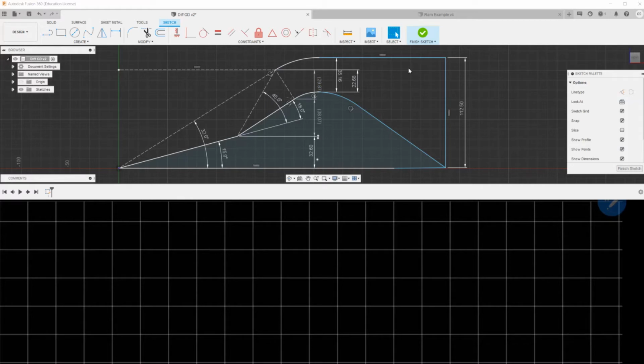When the inlet part of the diffuser is too much constrained, it cannot sustain the value of the mass flow rate that you would like to push through the diffuser because of a very small throat. It cannot push, and it creates a lot of resistance inside this zone of subsonic flow, and flow stops.